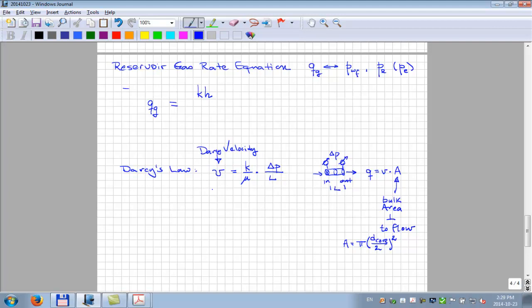So it's not equal to the, whatever you want to call it, pore velocity. If you looked inside a pore and caught a ride with a particle flowing along and measured the distance and time, you wouldn't have that velocity at all. So this is Darcy's law. And this is the permeability we're talking about here.